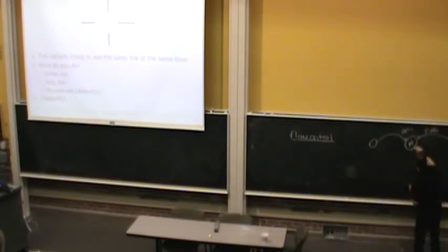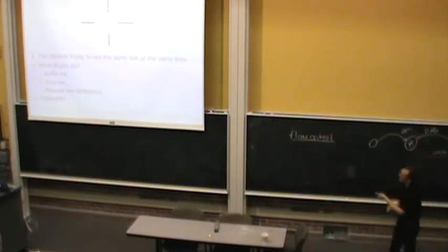And this home node, remember in the picture, sent a NACK saying that, too bad, I cannot grant you a request, send me your request again, later. And there's a design choice, of course. When does this node send the request again? Does it send right away? Does it wait for a while and send it? Those are all design choices. Another way of handling this would have been to buffer the request. That's the first part, right? So NACking is one option.